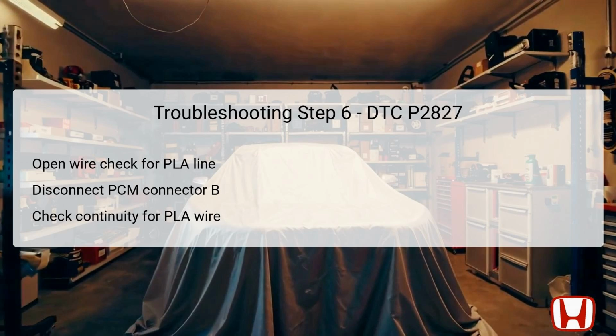If continuity is confirmed, it denotes that the PLA wire is intact, indicating a potential fault within the PCM itself, which may require replacement. Conversely, if continuity is not present, this confirms an open circuit in the PLA wire that must be repaired to rectify the issue.